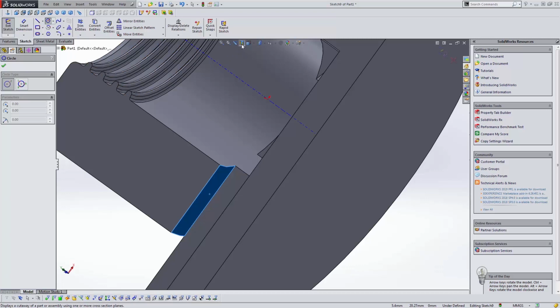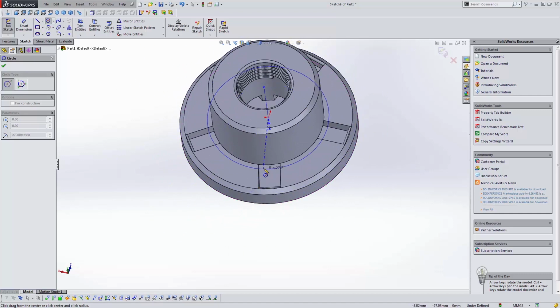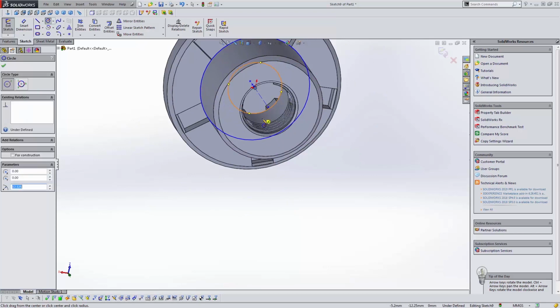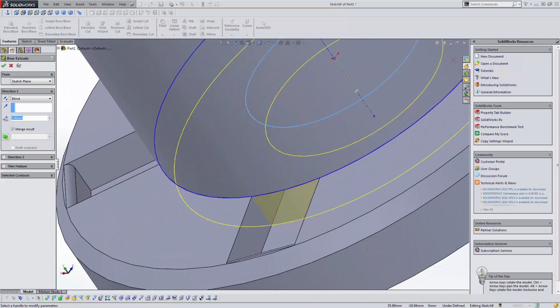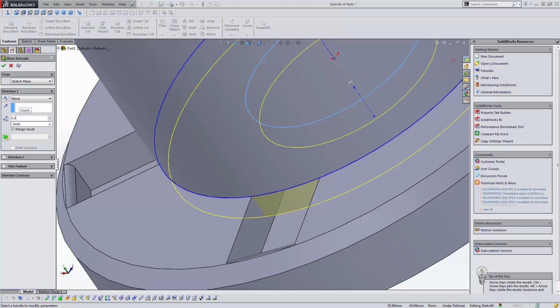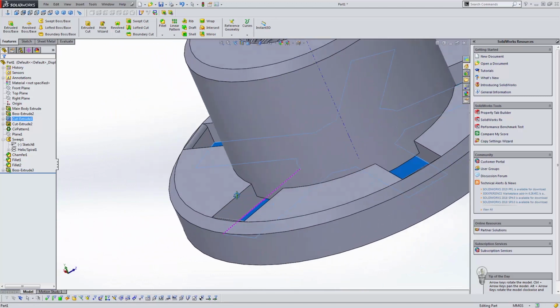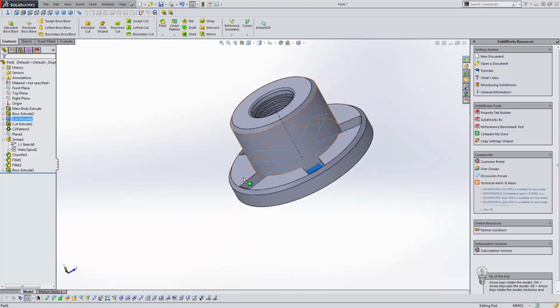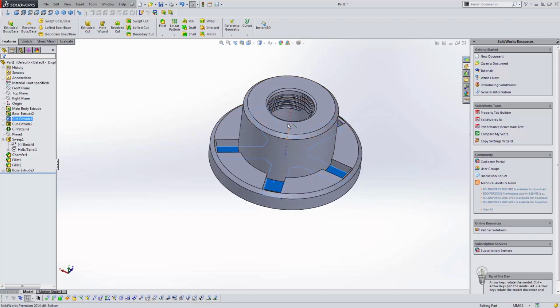So that surface is picked. I can get out of my cross section. So I'm still on that surface. And I'm going to basically draw a circle to the outer circle. I'm going to draw a circle to that inner circle. I'm just going to do an extrude and tell it to go down maybe 2 millimeters, maybe 3 millimeters, maybe 3.5. Just give myself a really small lip down there so that liquid won't have enough force to go over the edge, because it kept leaking. It would not stop leaking. Bad design. So this is iteration 2 that I'm going to try out.